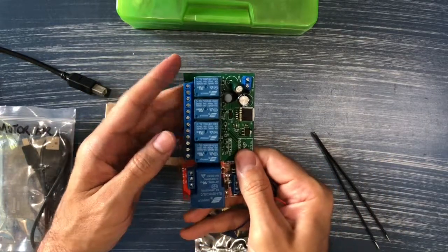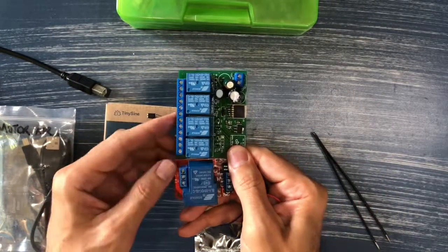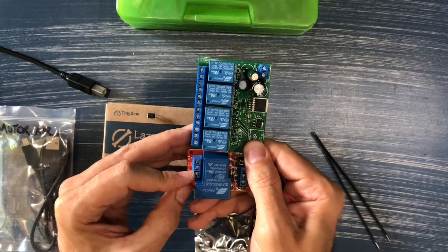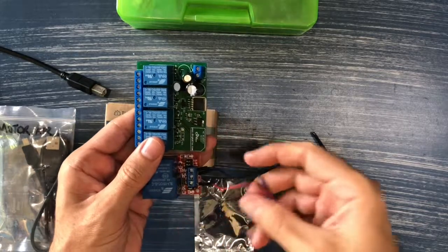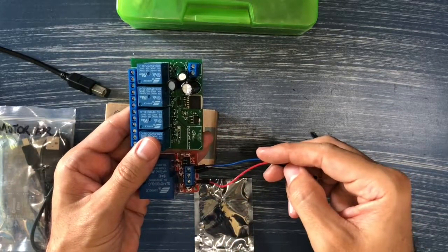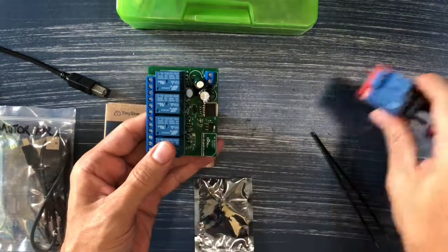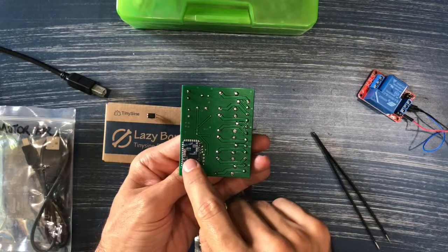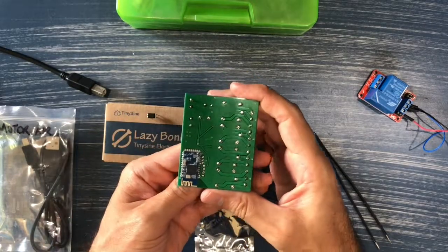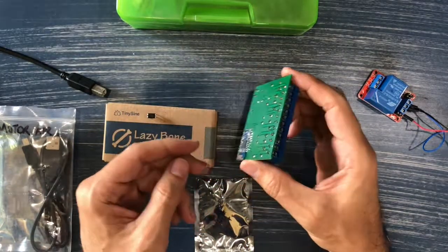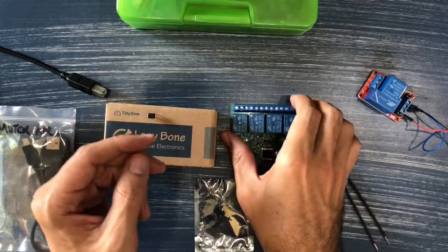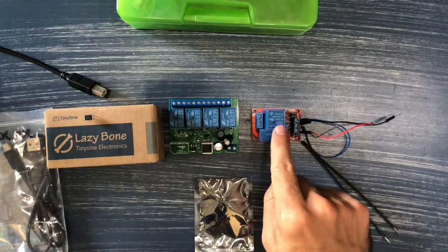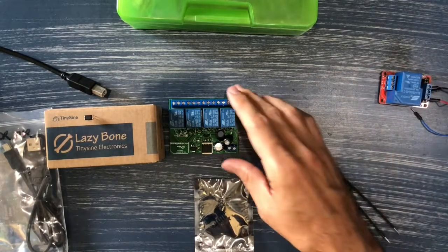But if we line this up, the high side is over here, where you connect the lamp or the motor. The low side, which is the one you're going to control digitally, in this case has no cables, as you can see. It's over here. It's actually a Bluetooth module. So what we can do with this is send Bluetooth commands from an Arduino and control all 4 relays. So this is much more flexible, much more robust.